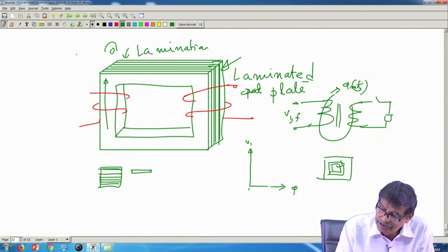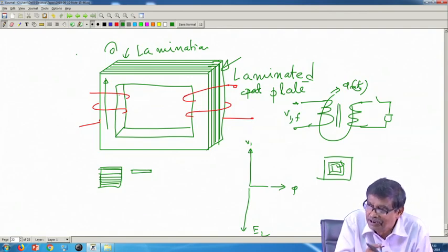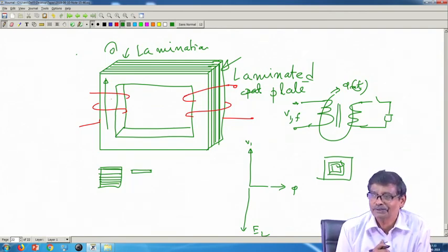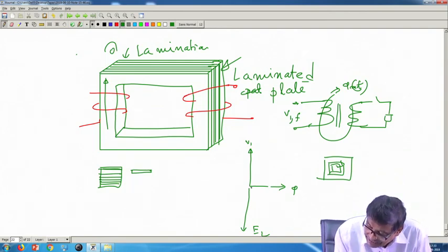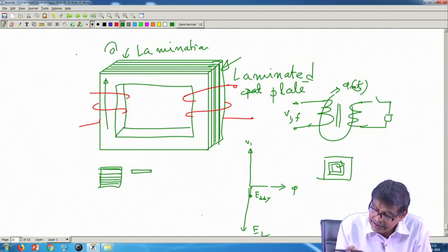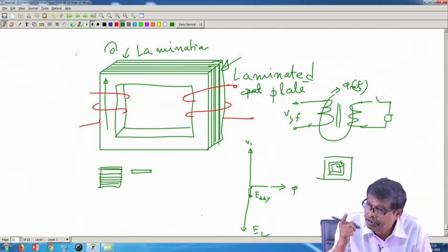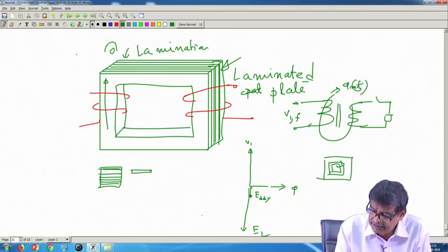There is induced voltage in the secondary too, that is there. But what I am telling is, there are some invisible secondaries already present in the core, and they had induced voltage also in the same direction. Why not eddy? And I assumed that the power factor of that eddy current path to be unity, neglecting leakage inductance.